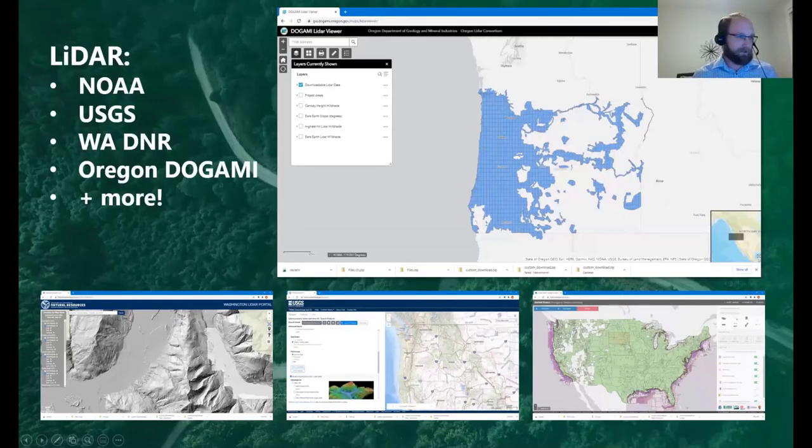So one of the caveats that I have on what I'm going to cover is the data sets that I'm using are going to be mostly LiDAR data sets. The reason for that is I get to talk with a lot of folks now from all over the world, and folks in the West Coast as well. And I'm frequently surprised by how many people are doing designs with hand traverse data, and there's publicly available free LiDAR coverage in their area.